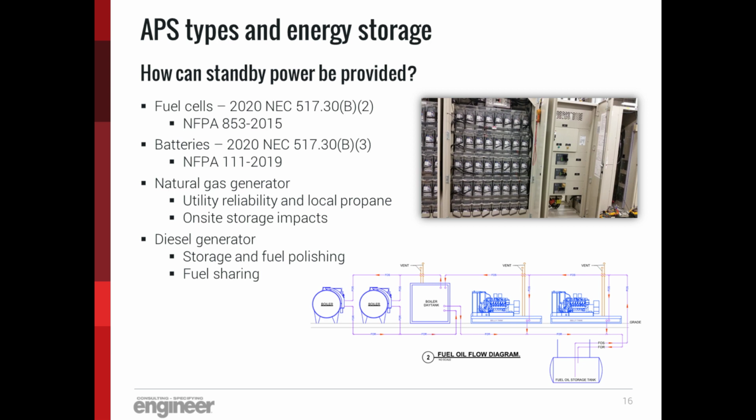Now, batteries are another concept. With the advent of electric vehicles and lithium-ion making a pretty strong play, we're seeing 15, 20-year lifespans with batteries. So is that allowed? Well, NEC 517.30(B)(3) does specifically list batteries and references NFPA 111.